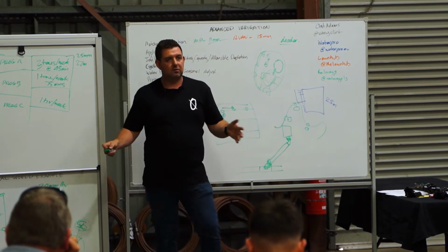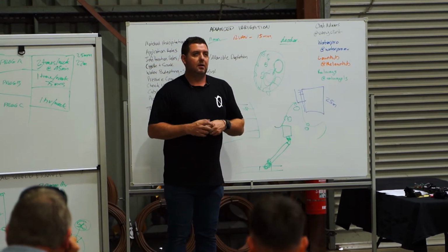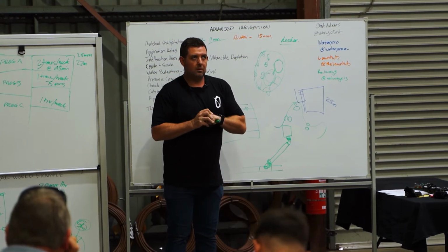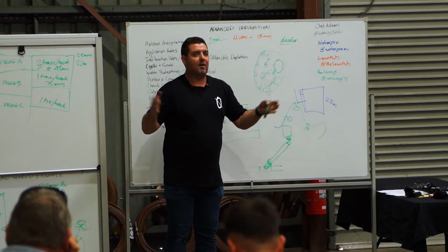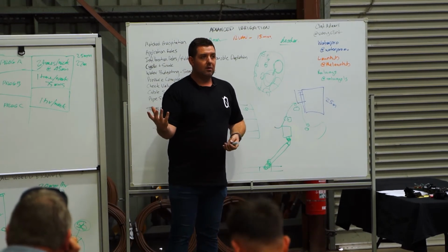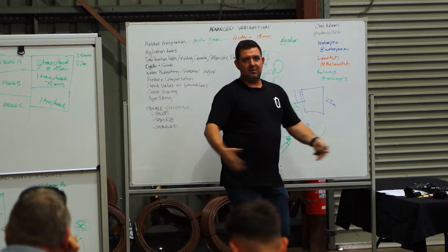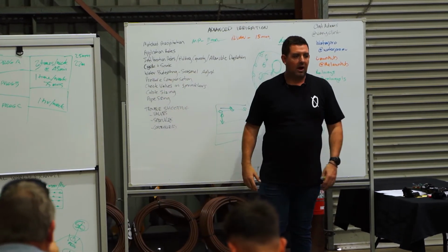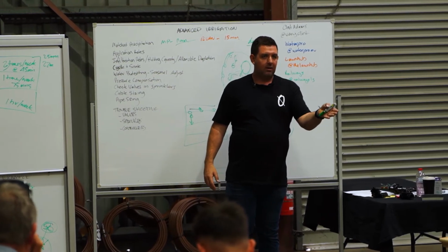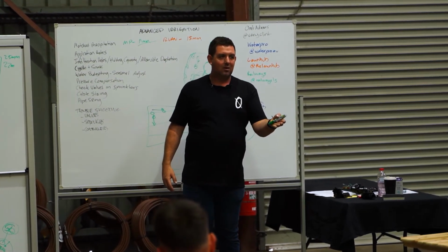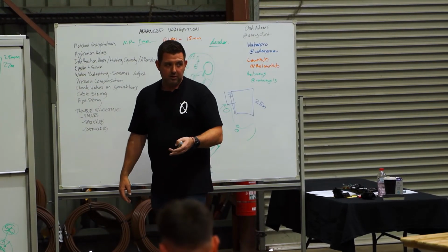The situation's usually so big that there's so many valves anyway, because there's not enough flow. Obviously each valve can only have 80 or 100 liters a minute, and you've got this need to water with 100 valves. 100 valves of multi-core is 101 cables. 100 valves of decoder is 2 cables.